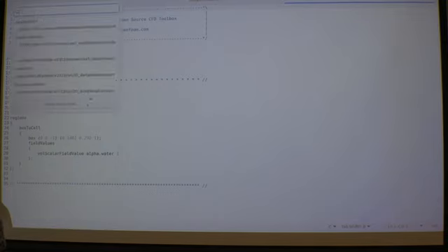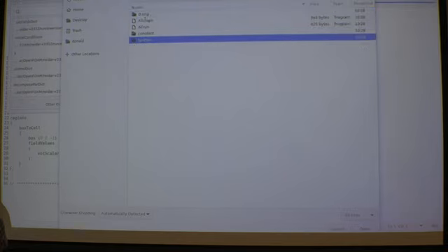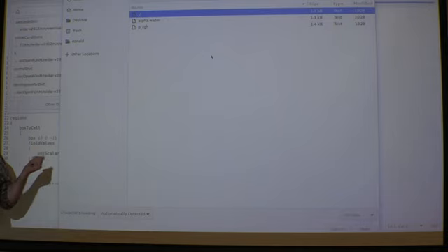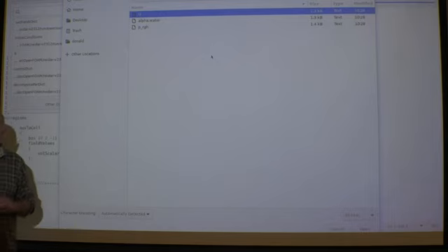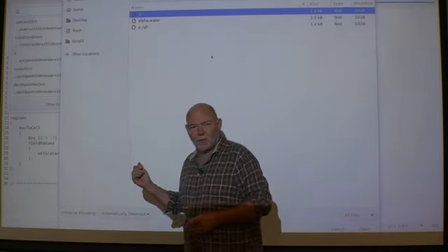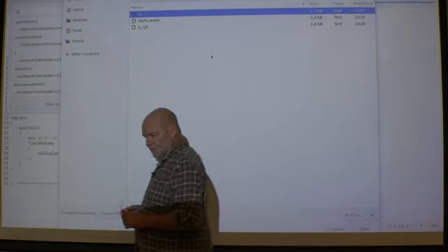Now, if we have a look at the 0 folder here, you see we don't have it, but we have a 0.orig. So let's have a look at that one. We have the U, and then we have not pressure, but we have p_rgh actually, p minus rho gh. What's that? Well, that is the pressure, but we have subtracted, say, the static pressure. And now it's a change. Normally when we operate with pressure in incompressible flow, that is pressure divided by the density. That's not the case anymore. This is the real pressure in Pascal. So be aware of that one.